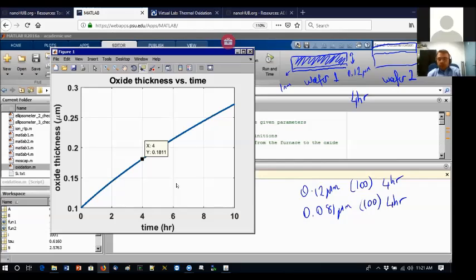So, why did we grow less? Actually, we already discussed this. We grew less because the oxidant coming from the top was having a difficulty to penetrate the whole thickness here. So it's going to grow less at a slower rate. So that's why if you have an initial oxide, the end result will be different, and it's not a linear system. That's what I want to emphasize. It's a nonlinear output.